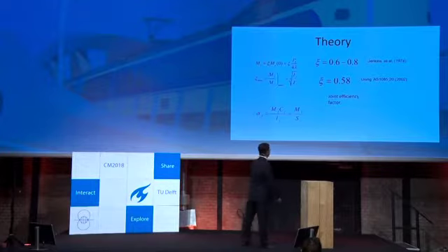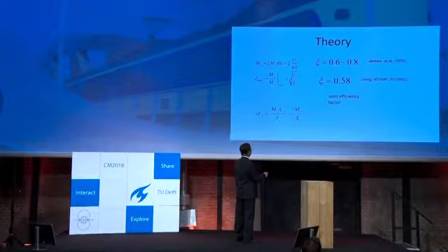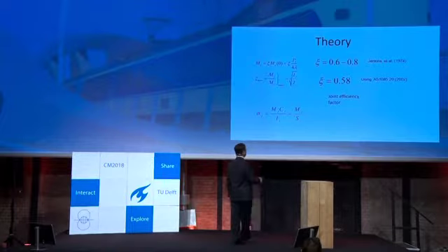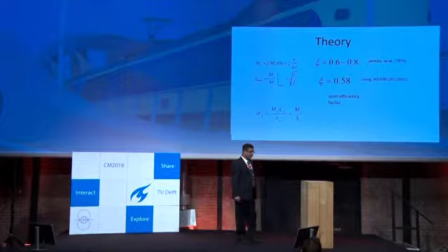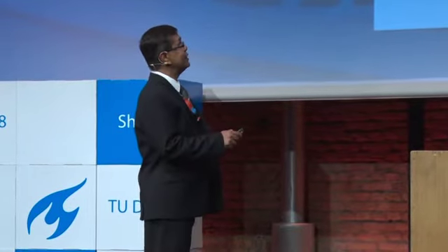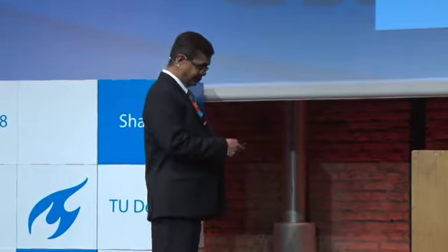This factor is established in the literature by Jenkins, and it is 60% to 80%. So I analytically calculated this joint efficiency value using the Australian Standard 1085, 2002, and I calculated it as nearly 60%, which is so close that it can be comparable. So this is the analytical benchmarking with the established value in the literature.